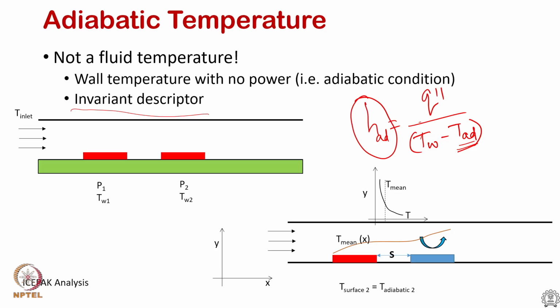make use of the same profile, and so analytical solutions are feasible, or at least a framework using the unheated starting length becomes very feasible if you allow for unheated starting length or arbitrarily varying temperature distribution, because we are playing with the idea of heat source turning off, turning on, and that can be easily achieved with a simple code. So, moving forward, if we had another heat source, no problem, you turn that off, see the adiabatic temperature of this by turning that off, and go on measuring similarly and measuring a heat transfer coefficient. What is this going to do?